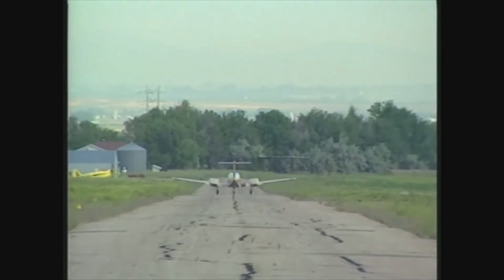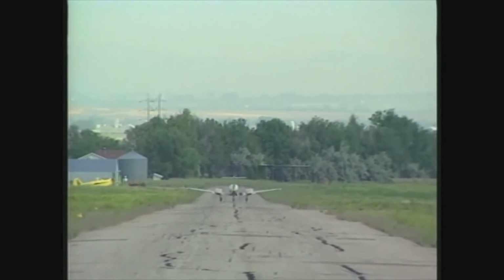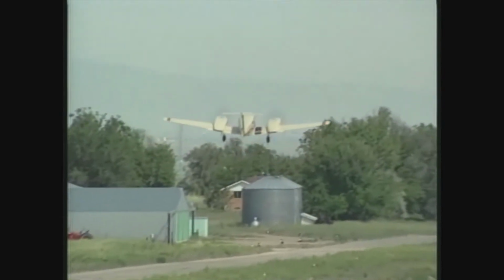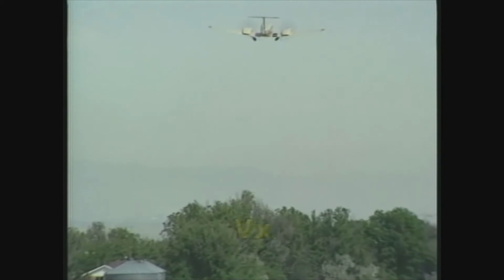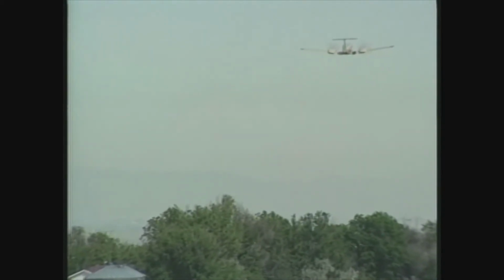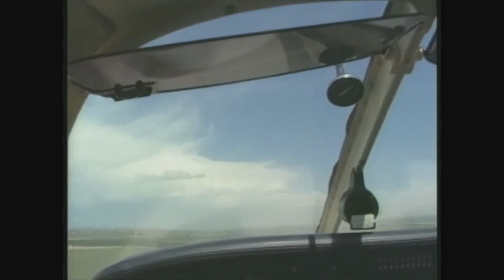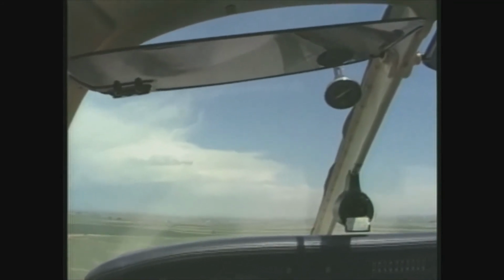Accelerate to the recommended liftoff speed, or VMC, plus 5 knots, whichever is greater. Rotate firmly and accelerate to the best angle of climb speed, VX. Retract the gear when you have a positive rate of climb and can no longer land on the remaining runway. Once you have cleared the obstacle and reached a safe maneuvering altitude, establish the pitch and power setting for a best rate of climb airspeed, VY.